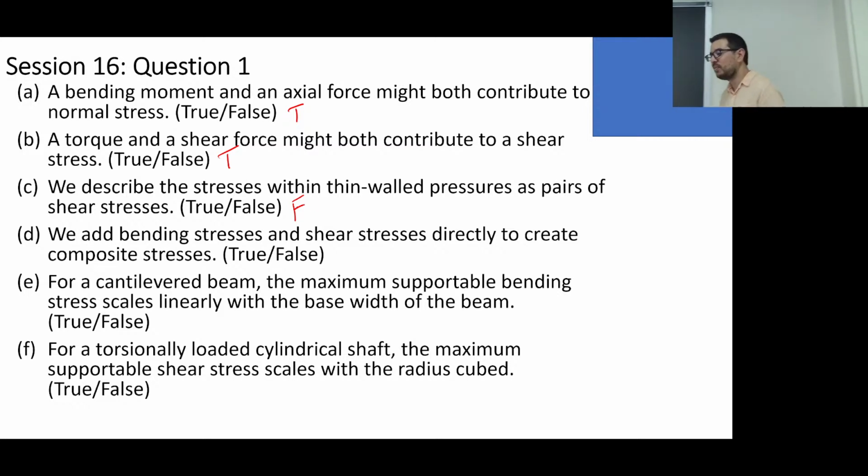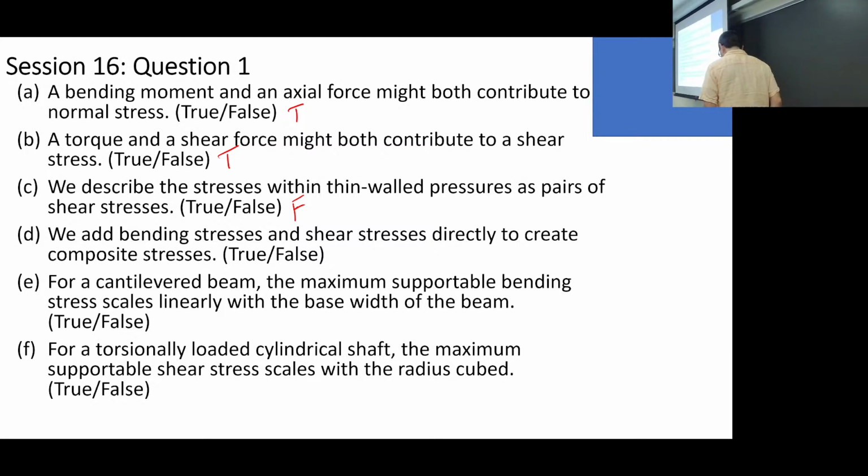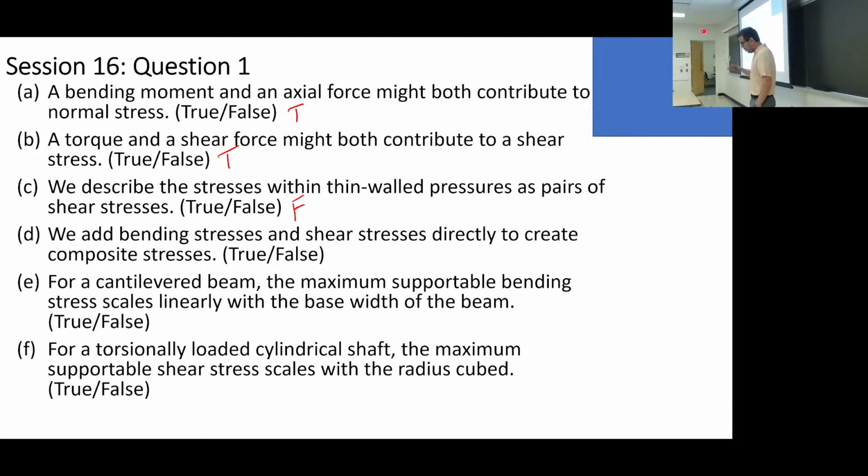Are there not any shear stresses in thin wall pressure vessels because the whole thing is expanding at roughly the same rate, so the material isn't rubbing against each other? Okay, we will come back to this. We will think of equivalent shear stress, because if it's a ductile material, like a lot of the metals we're thinking about, the reason it fails is actually because of shear stress, not because of normal stress, okay?